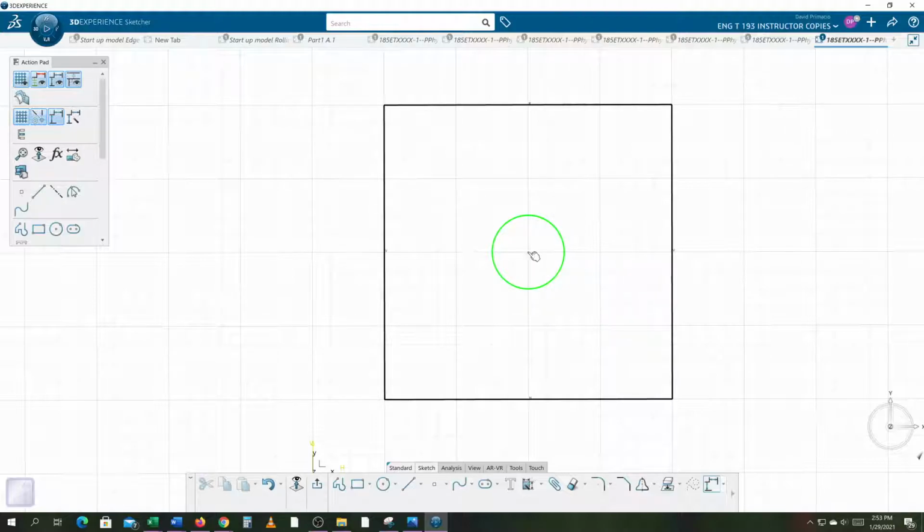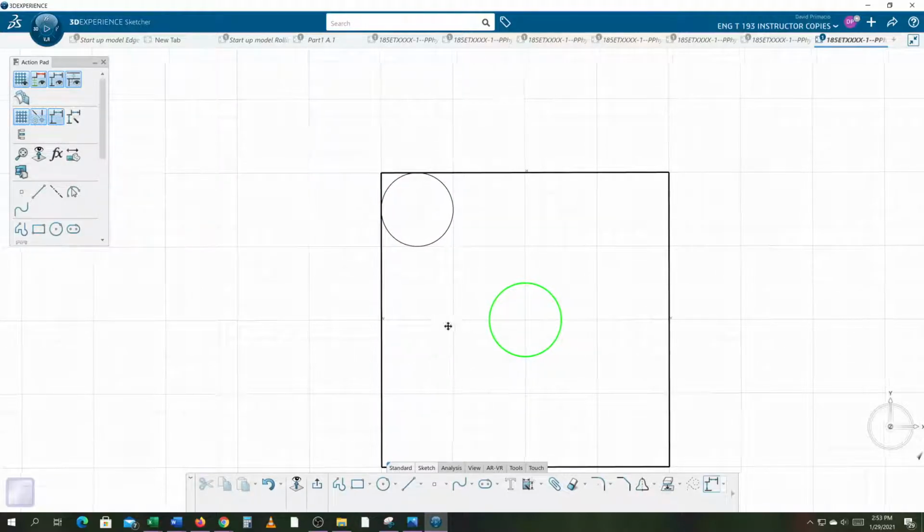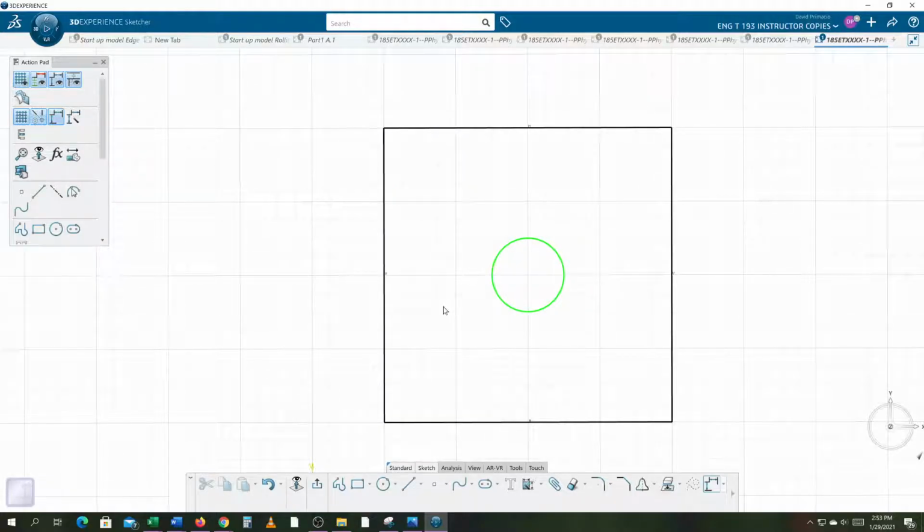So if this cutter were to go over here and start machining down here on this corner, say, the cutter is going to land here, and it would be a 1/2 inch. In reality, even if I had drawn it sharp edges, if I use a 1/2 inch cutter, you're going to get that radius there. Okay, so in reality, what we did was we went and put in 1/2 inch radius. Again, this is a top view of the pocket, so now all my radiuses are 1/2 inch.